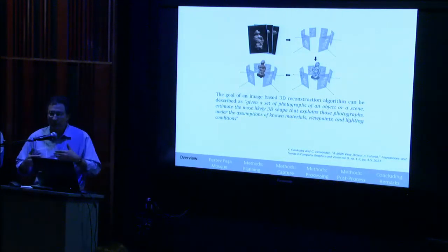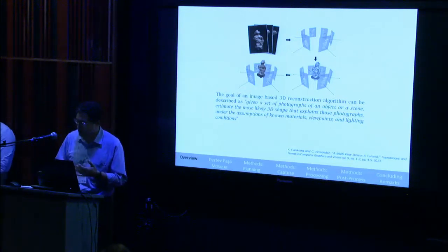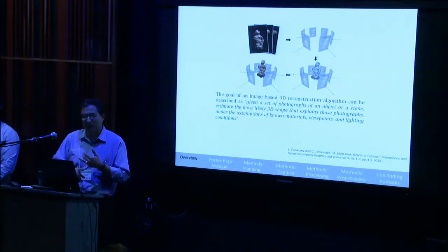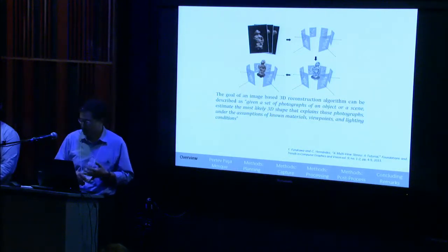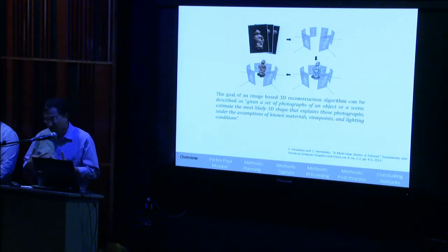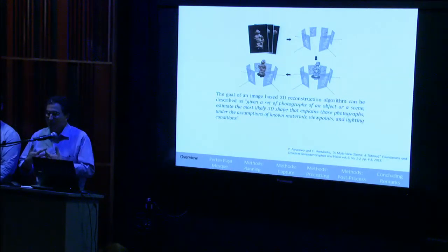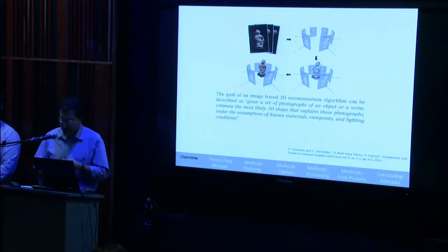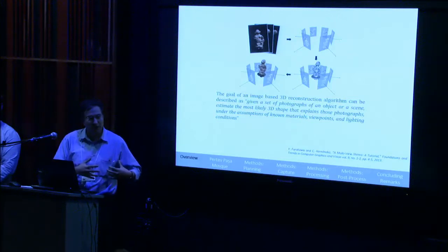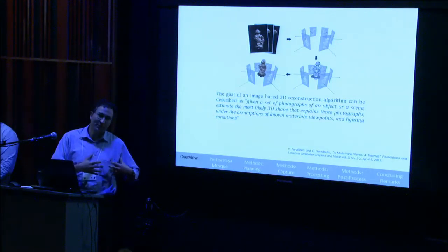So the fundamental process when you're dealing with photogrammetry and creating this three-dimensional shape is you're going to first collect your images or your photo sets. The computer algorithms will compute the parameters for each camera image. It will next create this matrix and finally construct a three-dimensional form based on that set of images. But it's also important to note that the accuracy of this final three-dimensional model is only as good as the quality of your images and the number of images that you use.